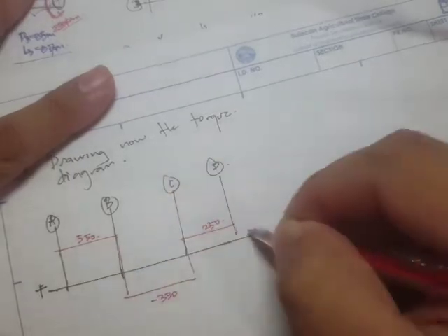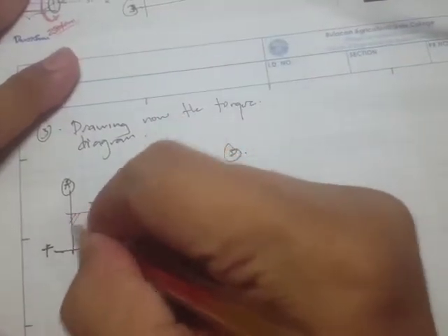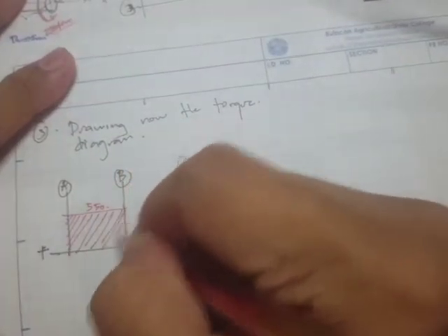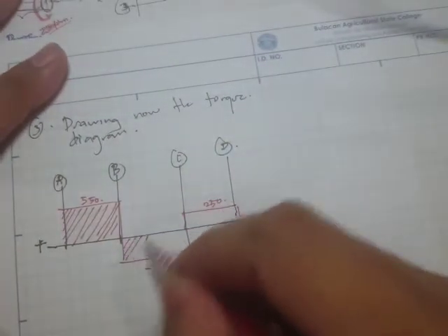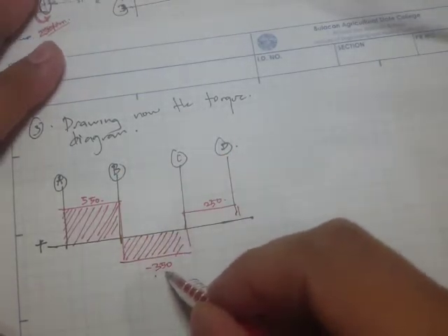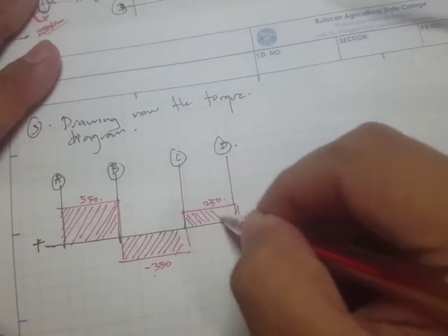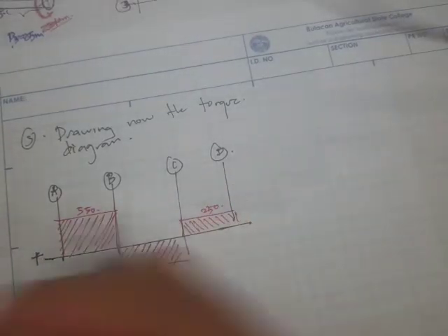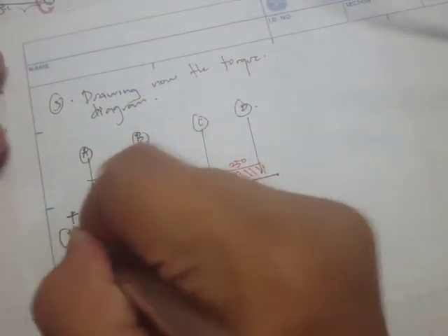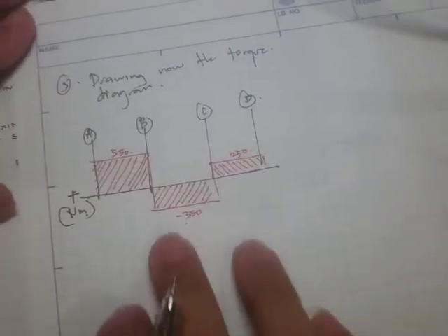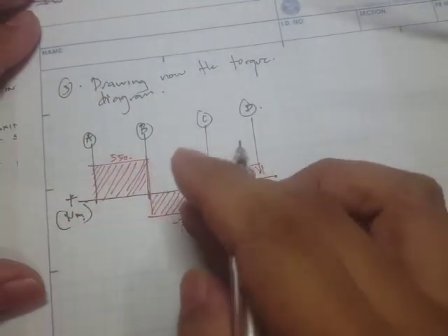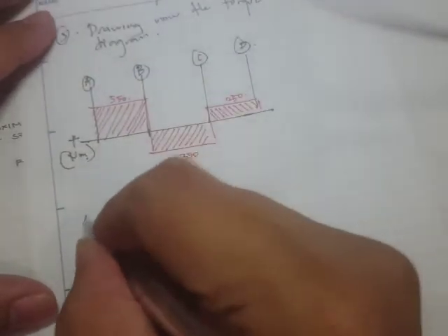Right? So this is going to be our torque diagram. From segment 1, from point A to point B, that's just 550. And from B to C, that's negative 350. And from C to D, that is 250. Let's write the unit. This is Newton meter. Okay, so now since we have these internal torques, then we can